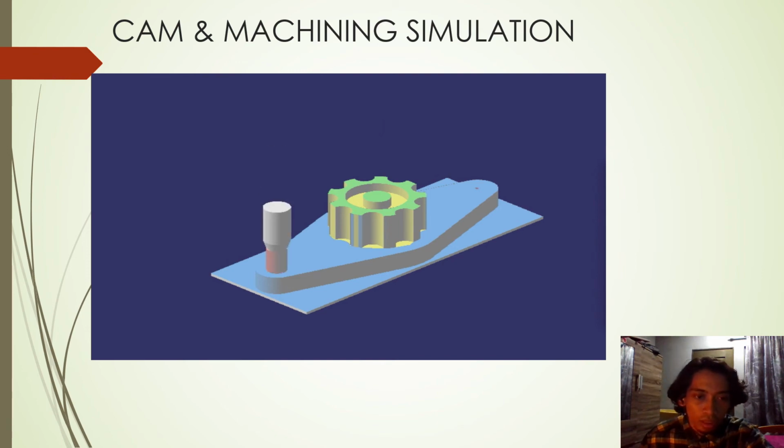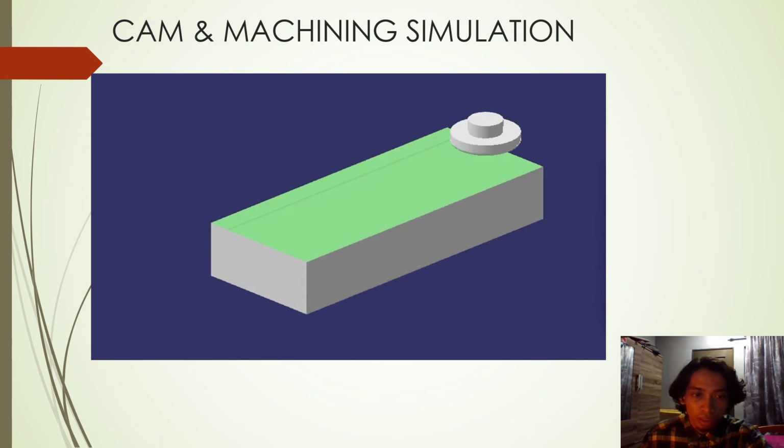So lastly, the deep hole drilling process using a 10 mm drill tool. For the last two processes, the jump distance is 5 mm, so that the cutting has a gap during both processes.